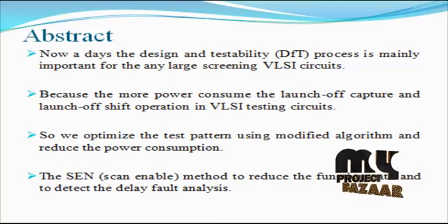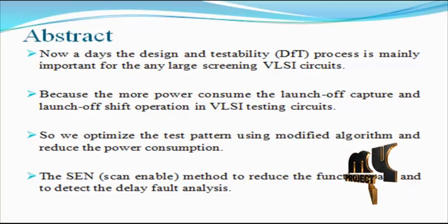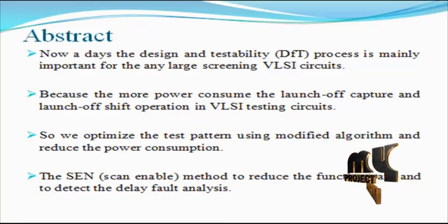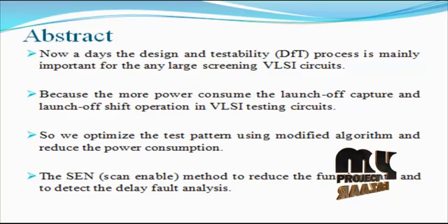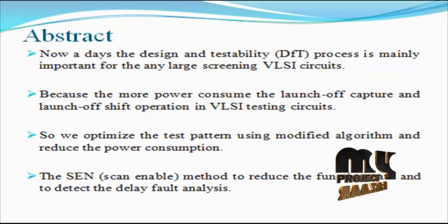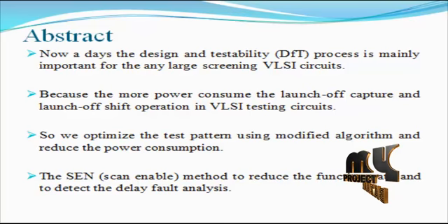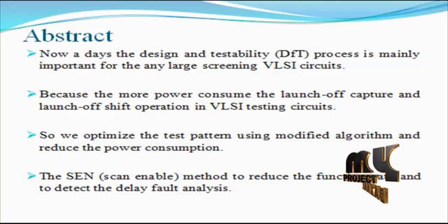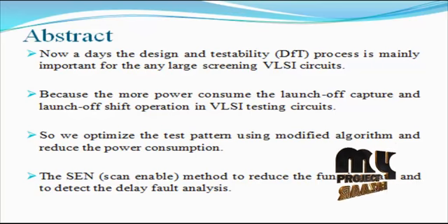Patterns optimized for quality and cost may thus end up violating peak power constraints, resulting in yield loss, while pattern generation under low switching activity constraints may lead to loss in test quality and or pattern count inflation. In this paper, we propose a design for testability support for enabling the use of a set of patterns optimized for cost and quality as is, in a low power manner.